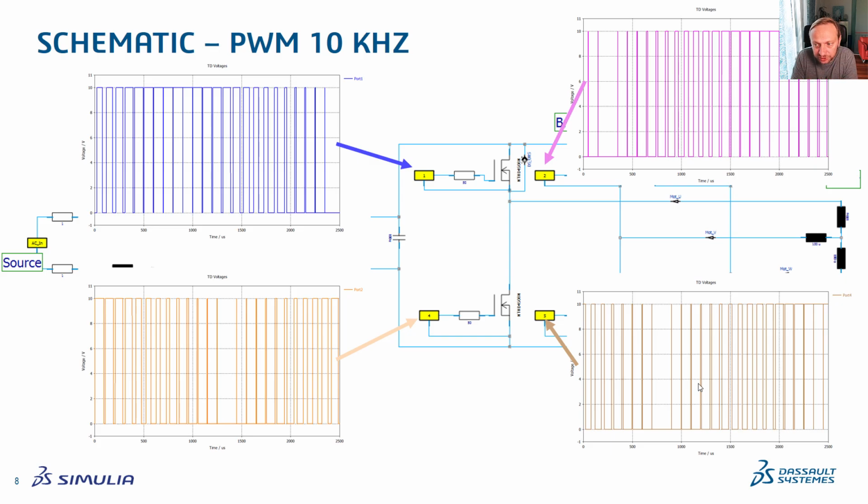So that's how typically such an inverter switches. I have just two phases shown here, the third phase is just not there because there is no space on the slide, but of course all three phases will switch with a so-called pulse width modulated signal, PWM for short. And these PWM signals typically are in something like the double-digit kilohertz range, so 10 kilohertz, maybe 20 kilohertz. Those are very typical values.